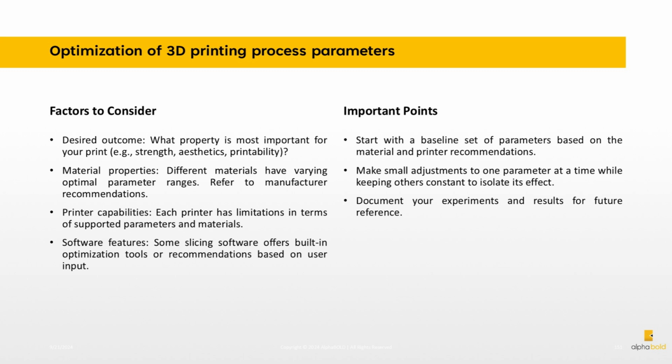Important points. Start with a baseline set of parameters based on the material and printer recommendations. Make small adjustments to one parameter at a time while keeping others constant to isolate its effect. Document your experiments and results for future reference.